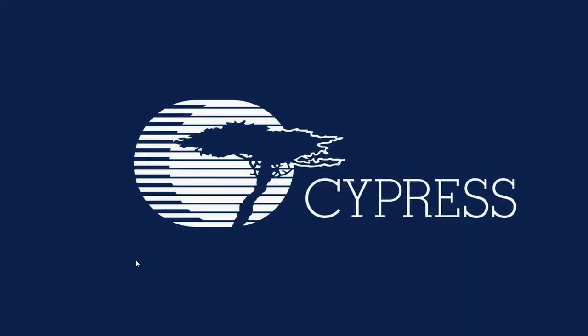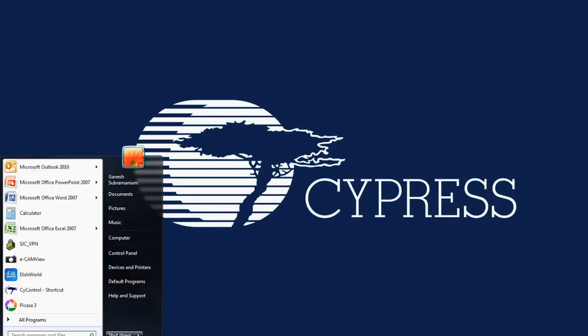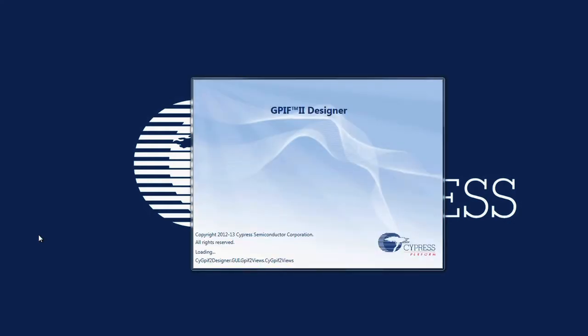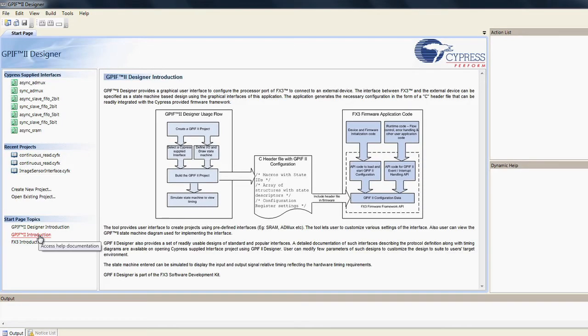Now let's examine how the software looks. I have the FX3 SDK installed on my computer, and I'm going to open the GPIF Designer. You will find that once it's open, it has three main tabs: one for describing the interface, another one for the state machine, and the third one for simulating the design that you might have built.